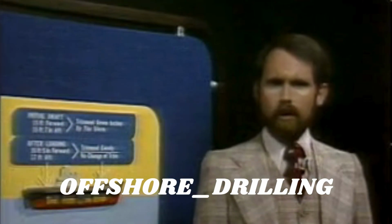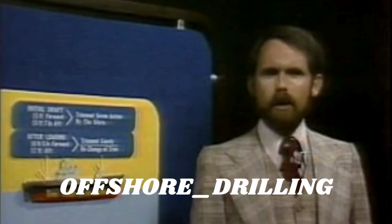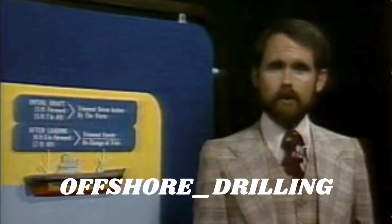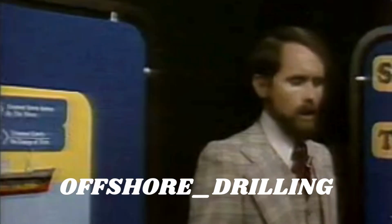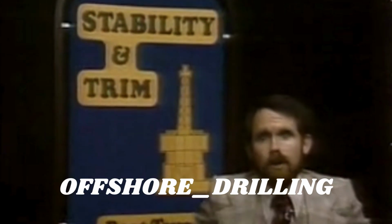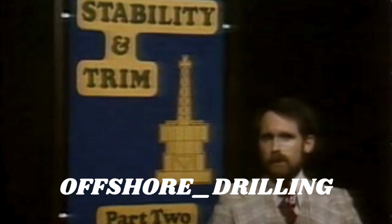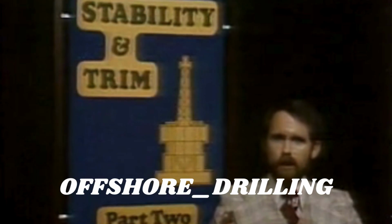Even before we load or discharge cargo, equipment, fuel, or any other weight, we can calculate what effect the operation will have on the vessel's trim. To do this, we use our old friend moments. Whenever a weight is moved through a distance, a moment is produced. When anything is loaded or discharged on a vessel, moments are created. The ship reacts to these moments by trimming, by the bow or by the stern.